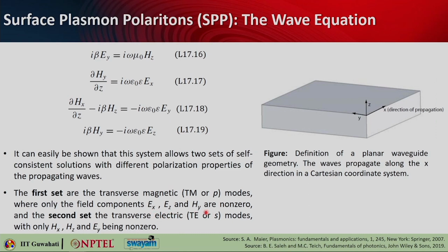These are the components which are non-zero. In the second set you are talking about transverse electric, or S modes. In this case, Hx, Hz and Ey are non-zero.